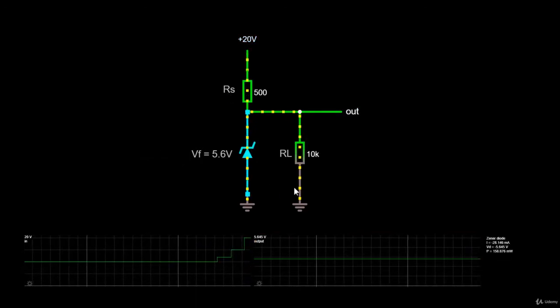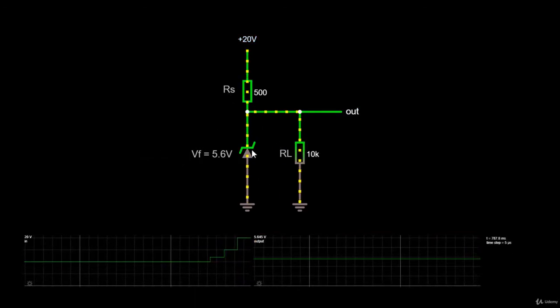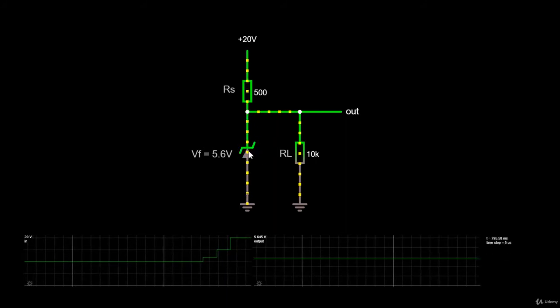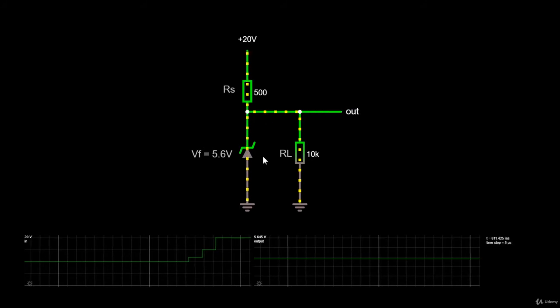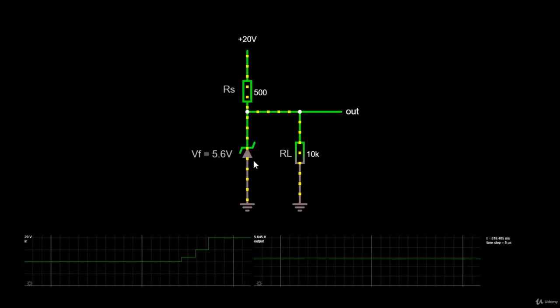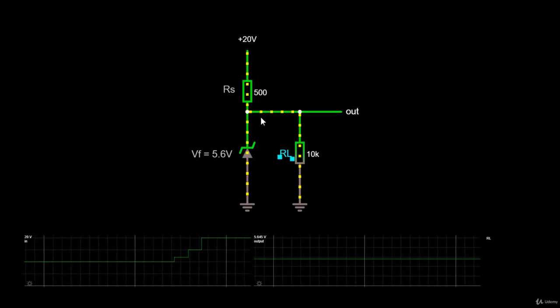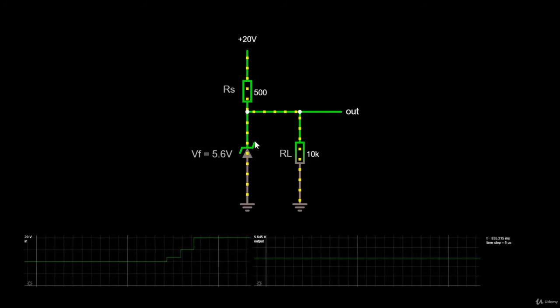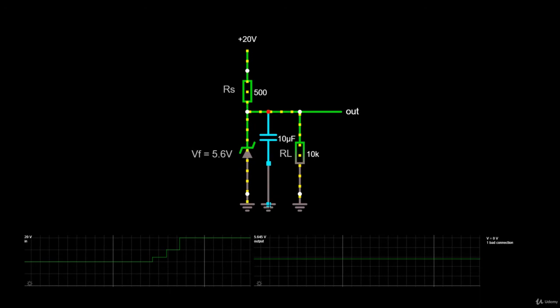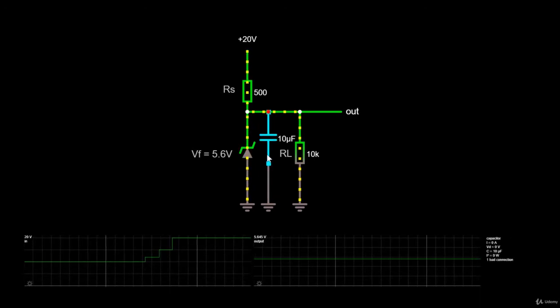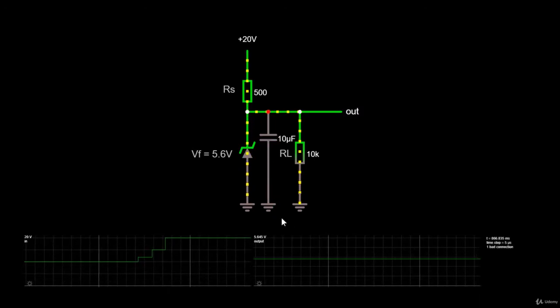One small problem with the Zener diode stabilizer circuits is that the diode can sometimes generate electrical noise on top of the DC supply as it tries to stabilize the voltage. Normally this is not a problem for most applications, but the addition of a large value decoupling capacitor across the Zener's output may be required to give additional smoothing.